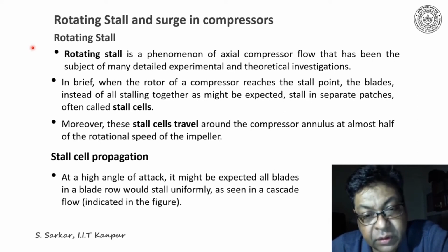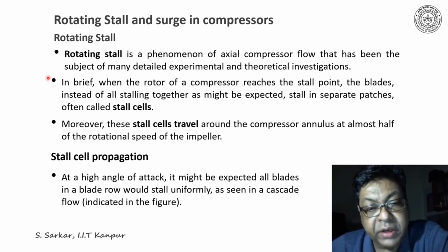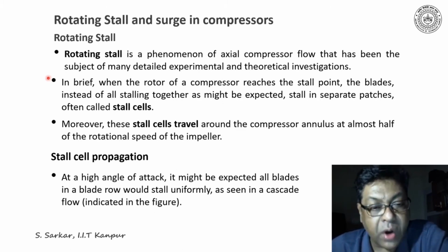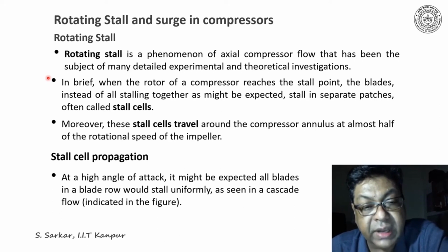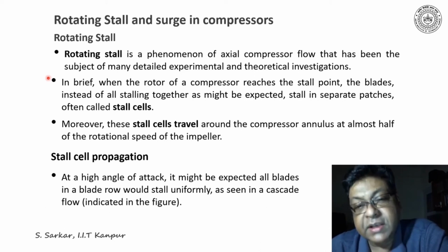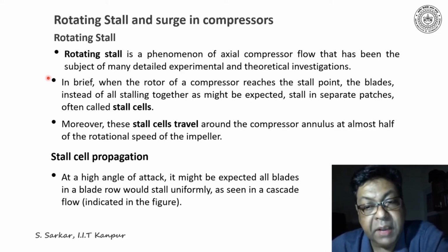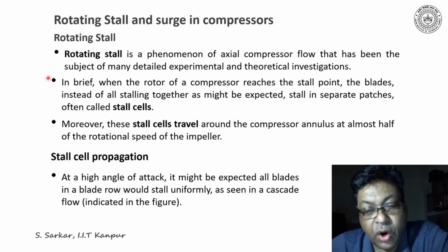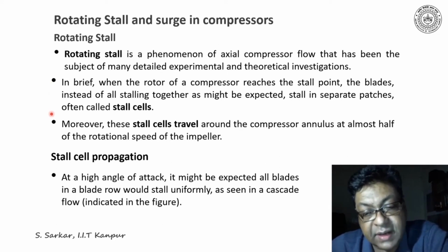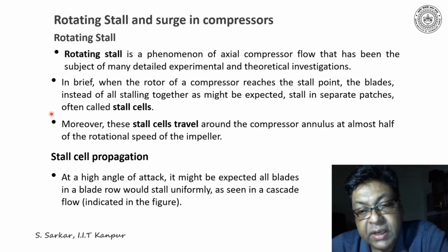In brief, when the rotor of a compressor reaches the stall point, the blades, instead of stalling together as might be expected, stall in separate patches, often called stall cells. Thus, stall cells are the patches of separated flow that occur within the annulus.